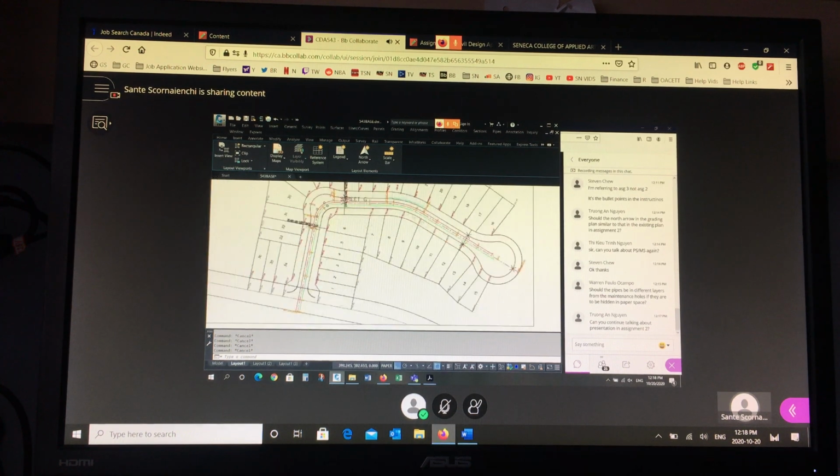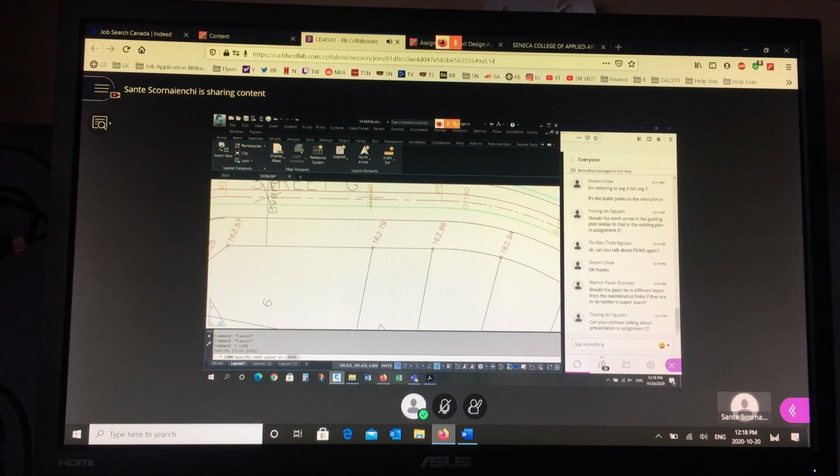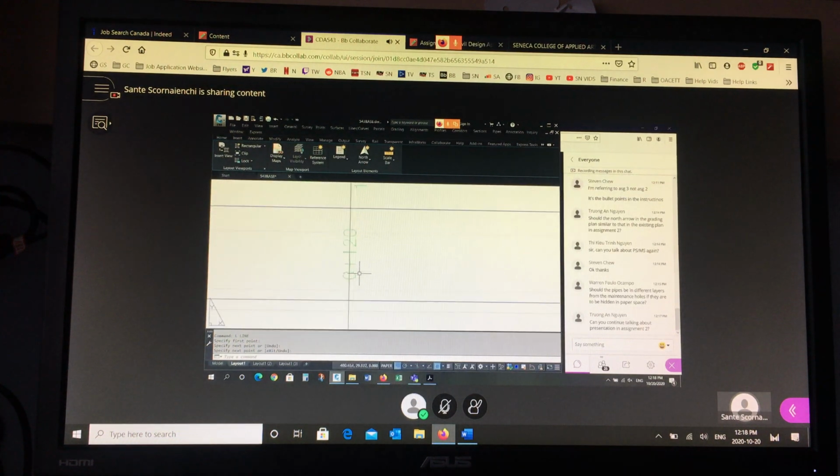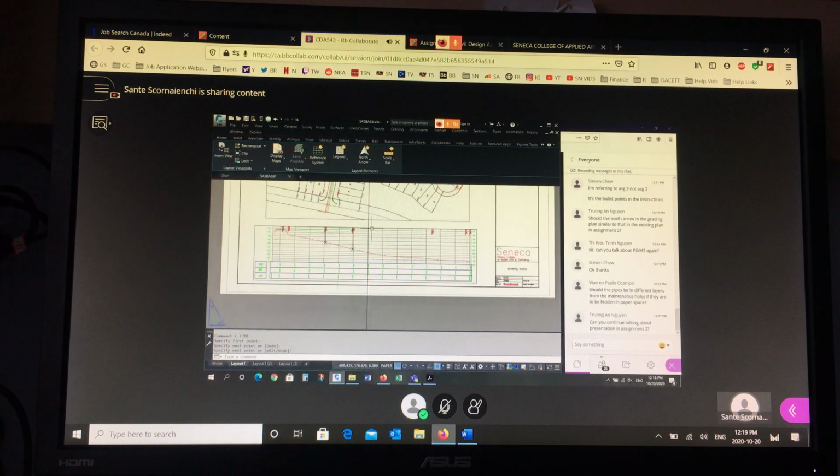And then if I draw a vertical line from this point here, station 120, it should go right through station 120 on the grid, right? Because you line this up to match. So I can check that you did that properly. So the scale and the horizontal piece of the alignment is directly above the profile for the same station range. That was the other thing I looked at.